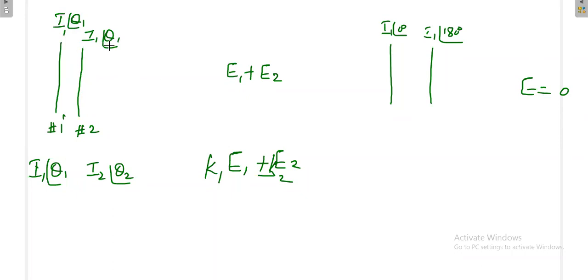So the antenna array is used to increase the gain of the antenna, in such a way that you supply your current and phase. And again, a question may arise: if I have an antenna like this, why can't I put one more antenna like here? Because once you bring one more antenna here, you will not get any gain, because you are simply increasing the length of the antenna. You will have some other impact, but you will not have increased gain.